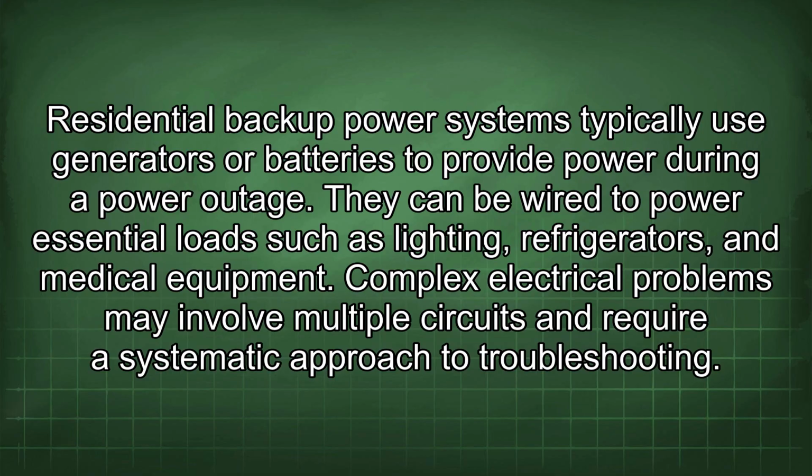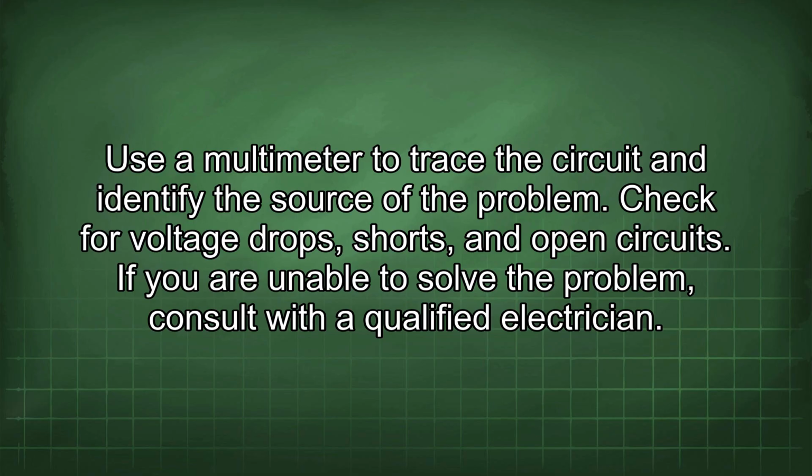Complex electrical problems may involve multiple circuits and require a systematic approach to troubleshooting. Use a multimeter to trace the circuit and identify the source of the problem. Check for voltage drops, shorts, and open circuits. If you are unable to solve the problem, consult with a qualified electrician.